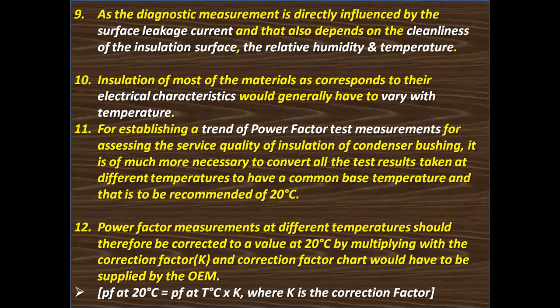As the diagnostic measurement is directly influenced by the surface leakage current, and that also depends on the cleanliness of the insulation surface, the relative humidity and temperature, that is atmospheric temperature or the environmental temperature.